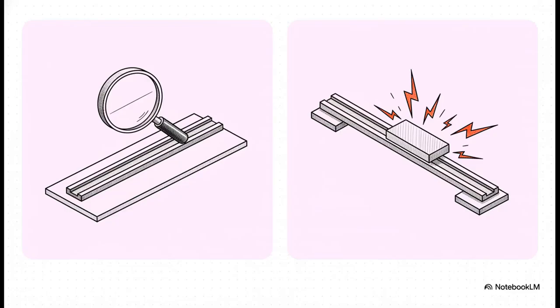Okay, picture this. You're manufacturing a linear guide rail. You measure it, check the specs, and hey, it's perfectly flat. It hits every single form tolerance on the money. But the second you try to slide its mating component onto it during final assembly, the whole mechanism binds up. It completely seizes. So why does that happen? Well, it's because while your rail might be perfectly flat, it is not parallel to its mounting surface.